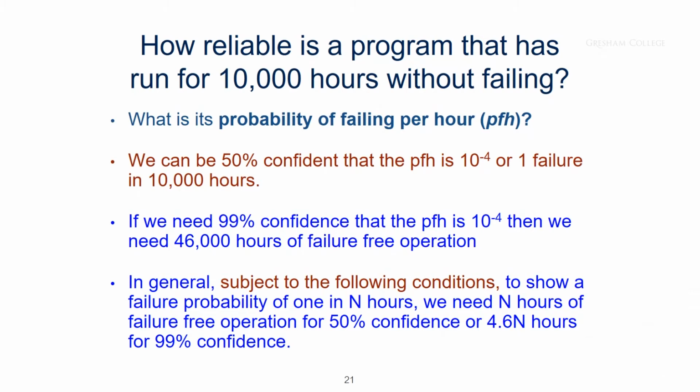If you do the stats on the basis of, as I say, 2 or 3 strong assumptions, it doesn't actually matter much which of the statistical distributions you choose to use; the answers come out sufficiently close that you end up with numbers that are close enough for engineering purposes. If it hasn't failed for 10,000 hours, there is a 50% chance that it won't fail in the next 10,000 hours.